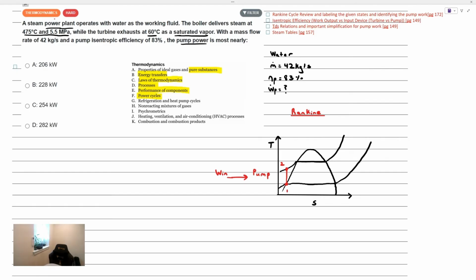We'll go ahead into the next system here, which is a boiler. The boiler basically increases the temperature of the water at a constant pressure until it hits state point 3. The boiler requires some heat input from a high temperature source. So we input heat energy into the boiler, and it increases the temperature of the fluid until it becomes a superheated vapor.